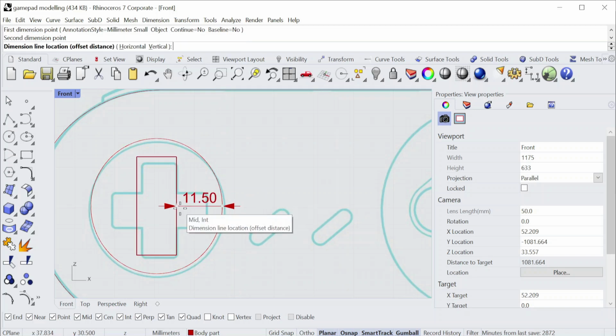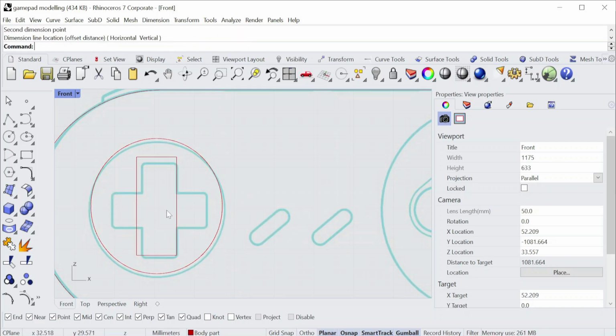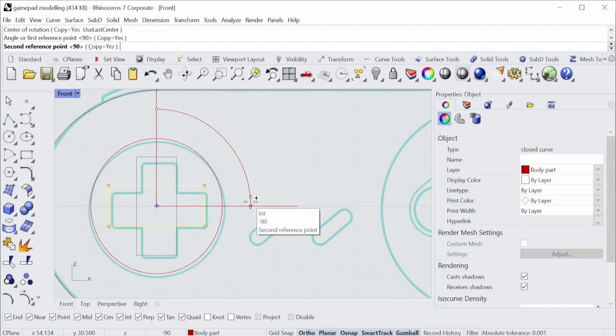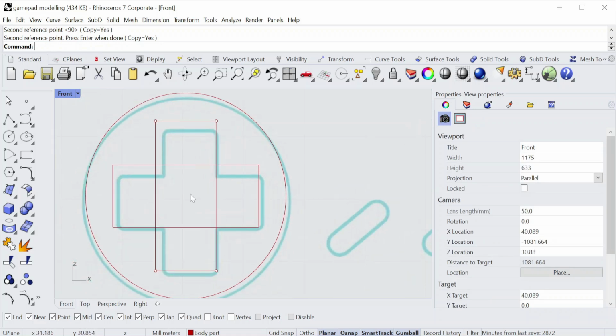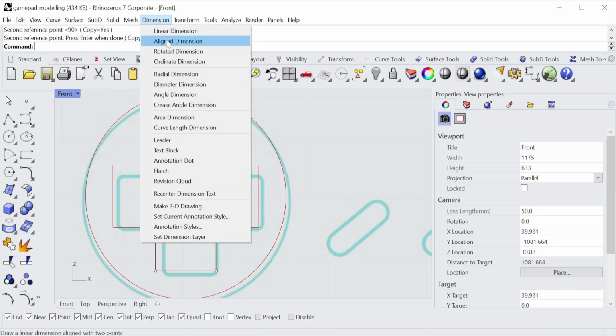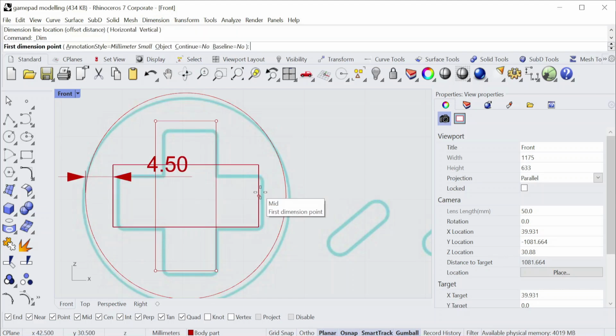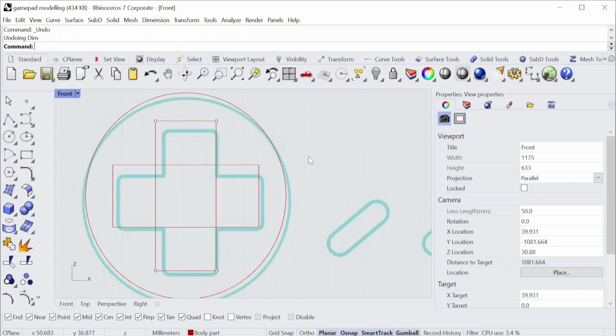Once the overall geometric shape of the game console is complete, we create two rectangle objects of equal length. The approximate length of one of them can be a piece 10 millimeters wide and 24 millimeters long. We make a copy of this piece, rotate it with the same center, trim it, and voila, the orientation arrows are ready. Now let's create their details.